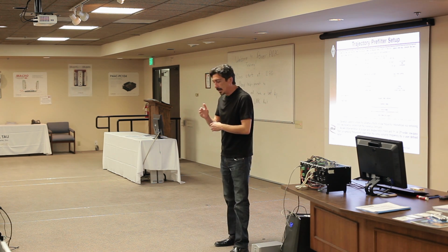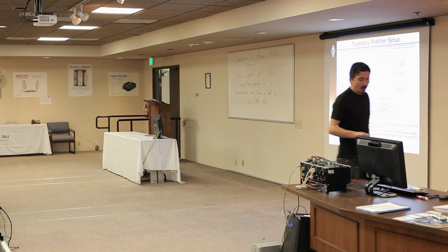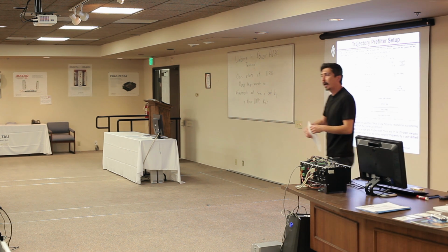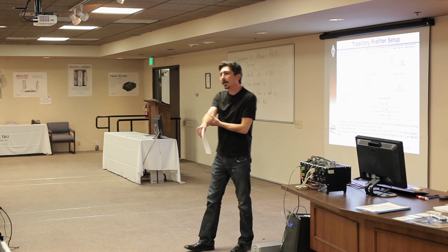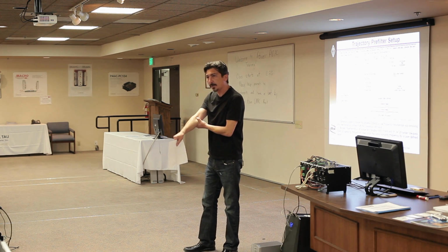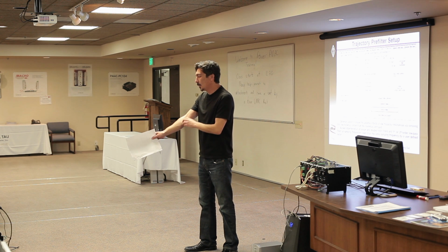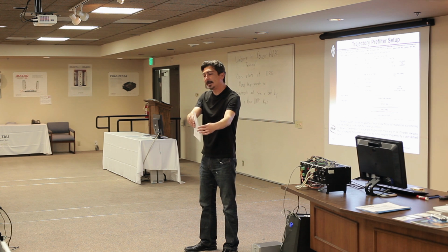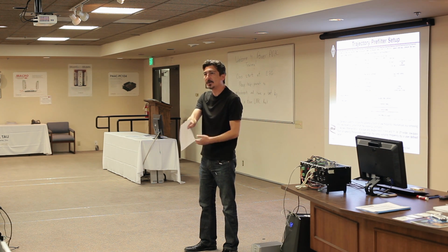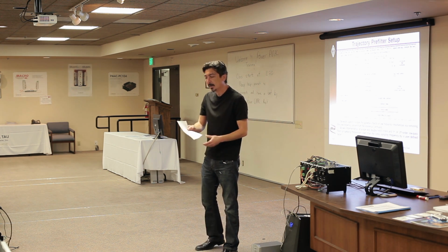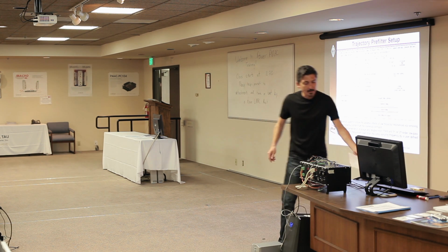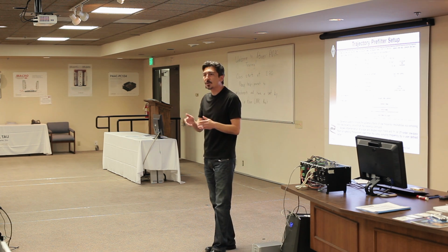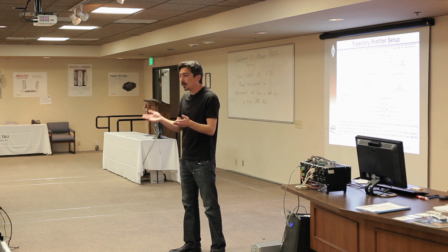But suppose, as a simple example, we have a really light robot arm, okay? And of course, it's being controlled at the wrist via the motor. As soon as you start to move really fast, you're going to see that the end vibrates due to the flexibility of the arm. So sometimes these frequencies are at really low frequency, like 10 hertz, 15 hertz. There are two ways to deal with it.